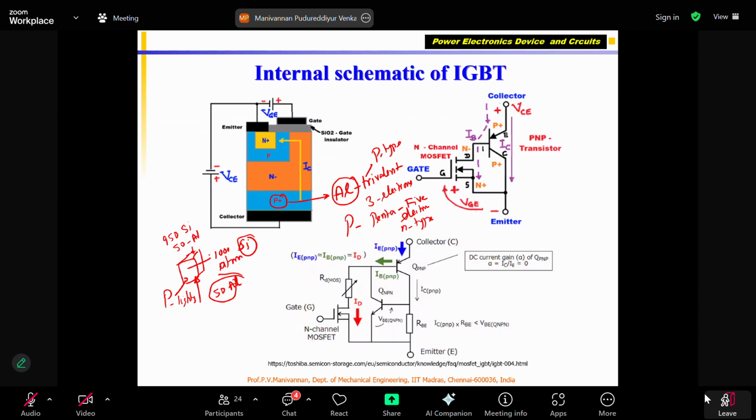Understand why 1000 atoms are in this one. In which I added aluminum, that means 50 silicon atoms are thrown out. I added 50 aluminum atoms. So that means this becomes p-type material. Instead, if I add, for example, 200 or 250 aluminum atoms, then what will happen? 750 will be silicon atoms, and 250 will be aluminum. So this is called a highly doped p-type material, a p-type semiconductor.